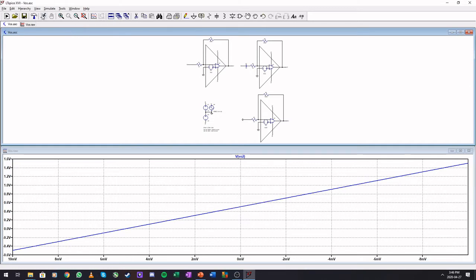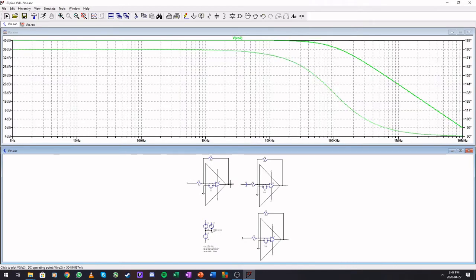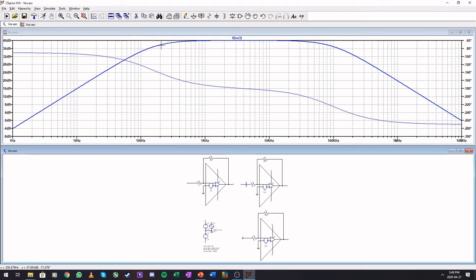Okay, lastly, if I quickly do an AC simulation, let's do this AC one, run it, have a look here. There is no low frequency cutoff. And if we look at the one with capacitor, here at about 160 Hertz, there is our minus 3 dB point. So adding the capacitor does influence our frequency response. So remember that when choosing a capacitor size here, the larger you go, the closer this will go to our 0 or DC point, where the bode plot does not account for DC. So yeah, just keep that in mind when adding the cap.